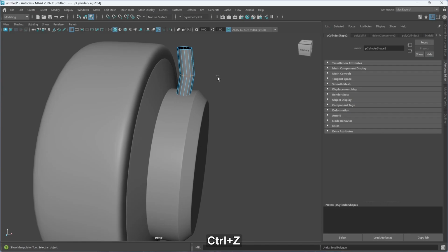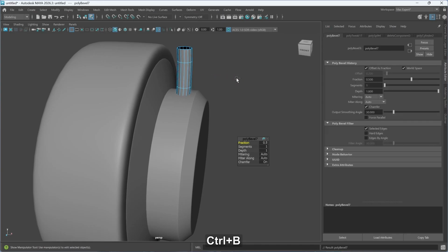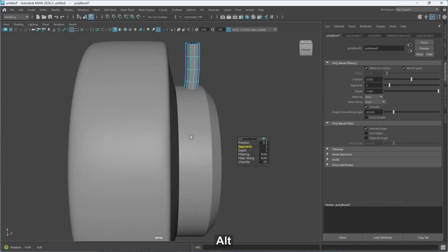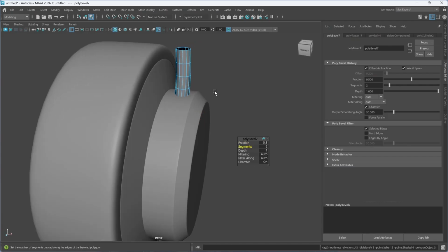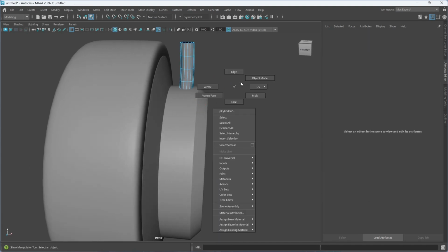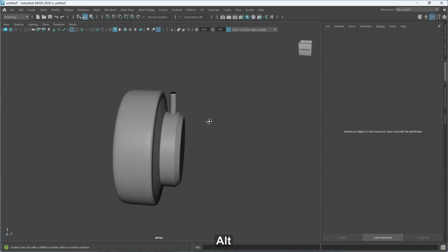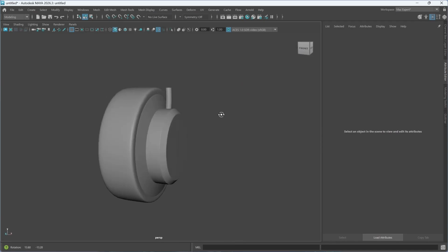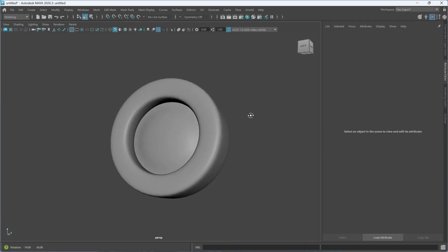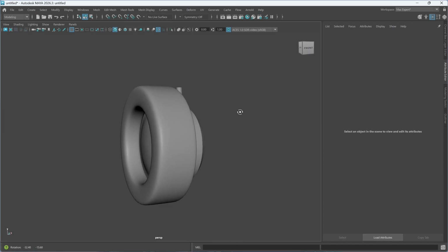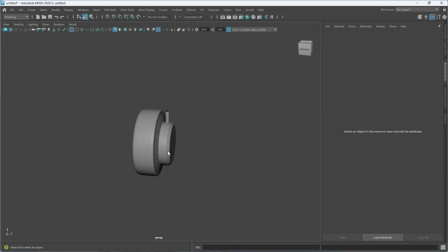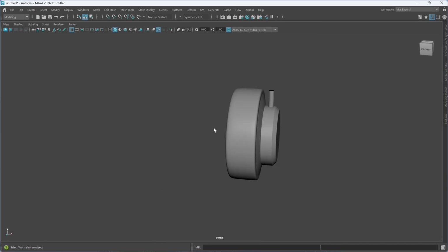So let's undo, hit W, push it forward just like that. Ctrl B to bevel, add segment. Yeah, this should work. Now we can hit 3, click and go into object mode. Alright, this is looking so good. Okay, now we can work with this. Let's go out of.